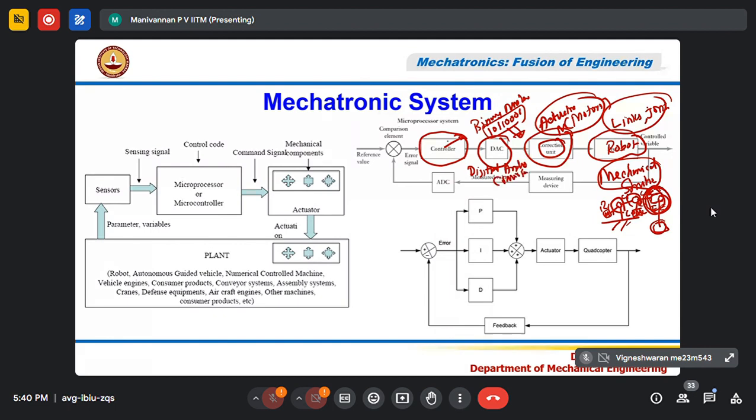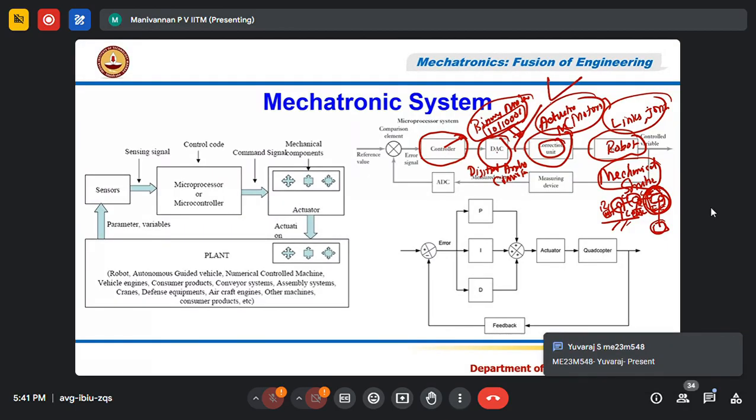The computer or embedded controller output is a binary number which cannot be directly given to any actuator, be it an electric motor or an engine. For example, to control a butterfly valve, a throttle control, you will use a DC motor or a servo motor. It wants a continuous 0 to 10 volts to open the throttle 0 to 100%. So you need an additional device called DAC, digital to analog converter. The binary number goes to the DAC, which in turn generates 0 to 10 volts.